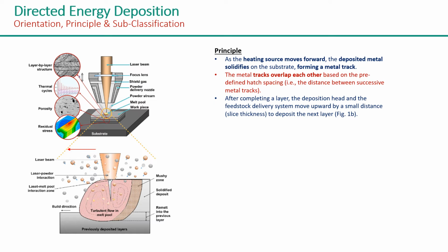So what is happening is that the laser beam is interacting with the feedstock powder material, and when it interacts, due to the energy generation, this metallic powder melts. When it is melted, it is deposited on the previously made base material, and in that way we get some specific height of the deposited layer, and we are forming a laser deposition.